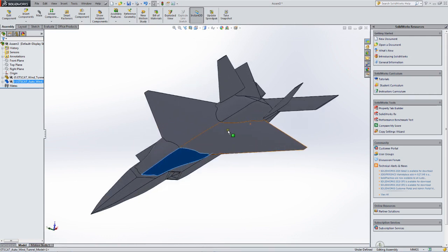We may still need to do a little processing. We certainly have to drill a hole. And those processes are just the same way they were as shown in one of the other videos about making wind tunnel models from your automatically defined geometry, automatically converted geometry into a CAD file. So you'd do the same things here. You'd save this assembly as a step file and then open that up and put the other wind tunnel features into it. This is also how you define a display model that didn't have bays open and that sort of thing. That could be a hanging model or a stand model that doesn't have landing gear and that sort of thing.